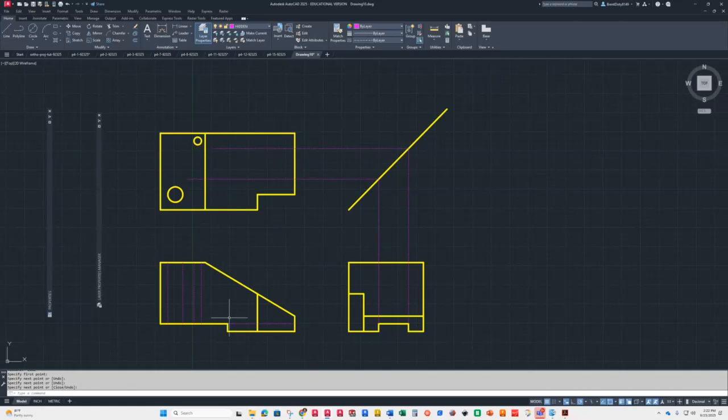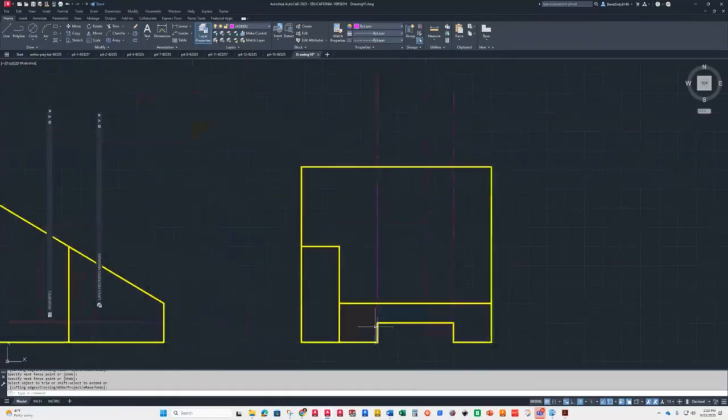You're saying, what do you mean somewhere over in there? Well, if you project this little notch here that's cut out on the bottom, it comes up here like so. And then you have to do some trimming, which obviously we can get rid of that. And then this right here, and that, and that. And see, this little piece here is right here and right here, which means I got something missing on this view as well. I should have a hidden line coming across like so.